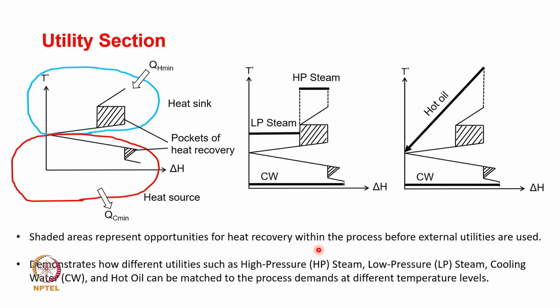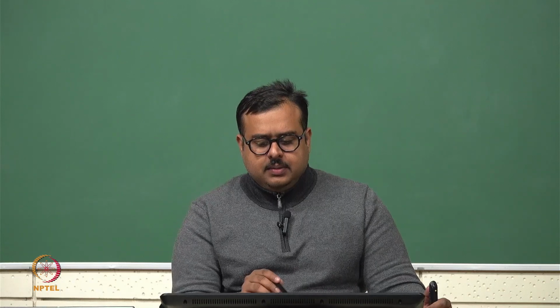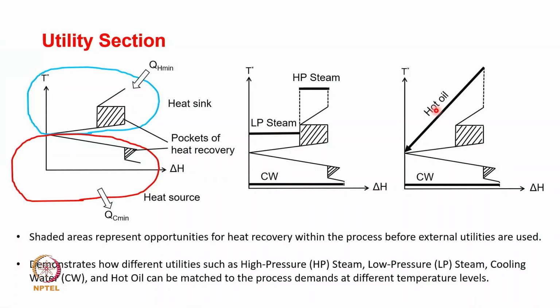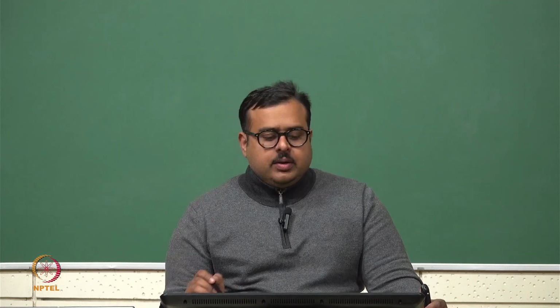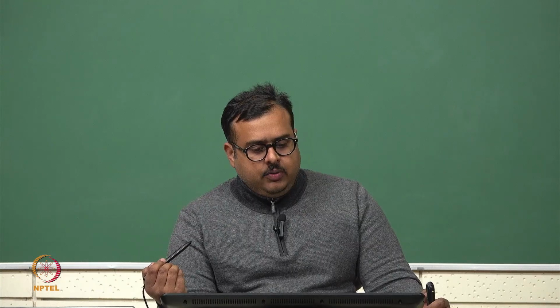And how can you do this? The hot utility can typically be an LP steam, or even a hot oil, and typically the cold utility will be mostly a cooling water stream. So once you have decided upon the utility to be selected, then now we can see